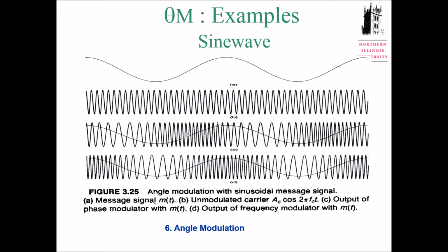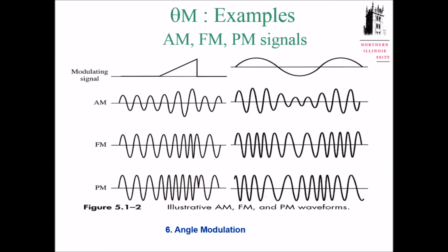So generally FM is a little easier to tell. The other one you can generally see is PM. So for FM, your frequency is proportional to your message. And for PM, your frequency is proportional to the change or the trend of your message. Okay, not required, but I will just tell you something.